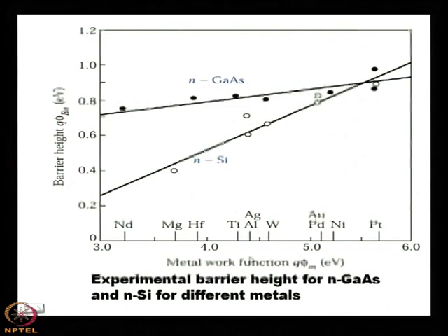So, if the variation is not wide, then why would you use metals like gold or platinum, because those are very costly? Just use aluminum or that type of thing, gold germanium or zinc, etc., that you can use. Another problem is that depositing gold and platinum is very difficult, because of the higher melting point of those materials. Normal thermal evaporation is not possible. So, these are the considerations.